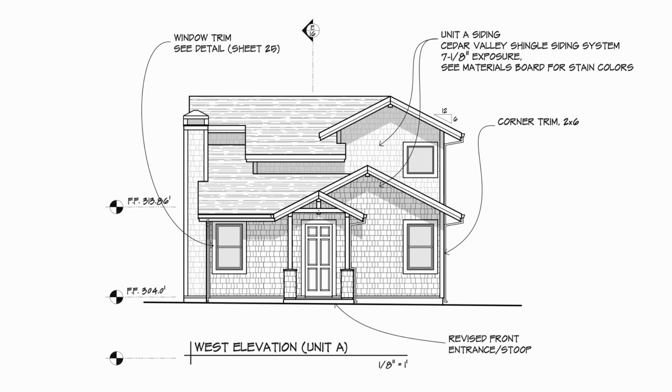This drawing, same elevation, a little bit more technical, but this is further back in the packet where we're trying to emphasize, hey, this is the type of shingle that we're putting in, this is what the corner trim is going to be, here's some elevation marks, just a little bit more technical detail. Notice, though, that there's a lot of line weights in this drawing. So we've substituted the color for all of the line weights. There's a little bit of shadow so you can see what's standing out, but it's really very much about line weights. And so I would argue that this is a line weight drawing. And I think there's probably 8 or 9 line weights in it. And anyway, this is one of the drawings that I did for this.